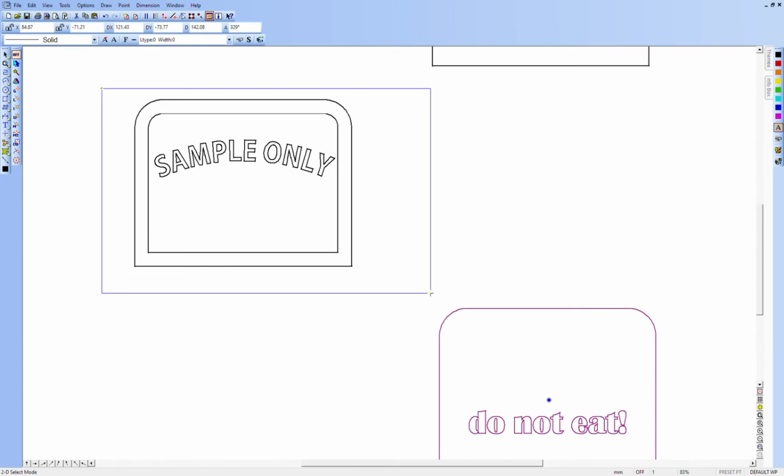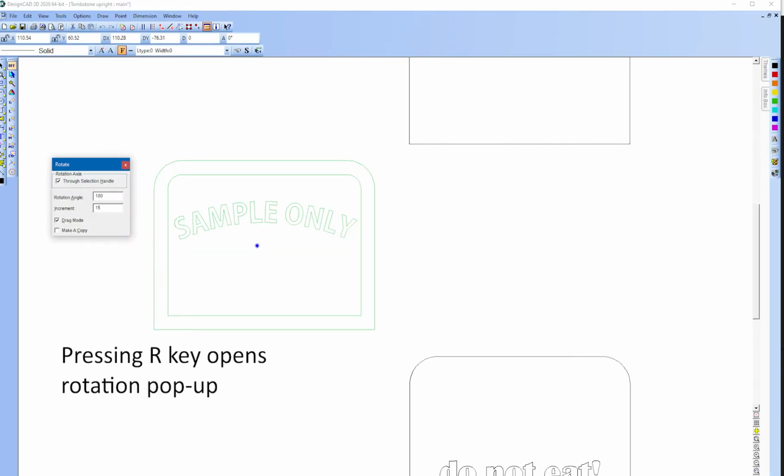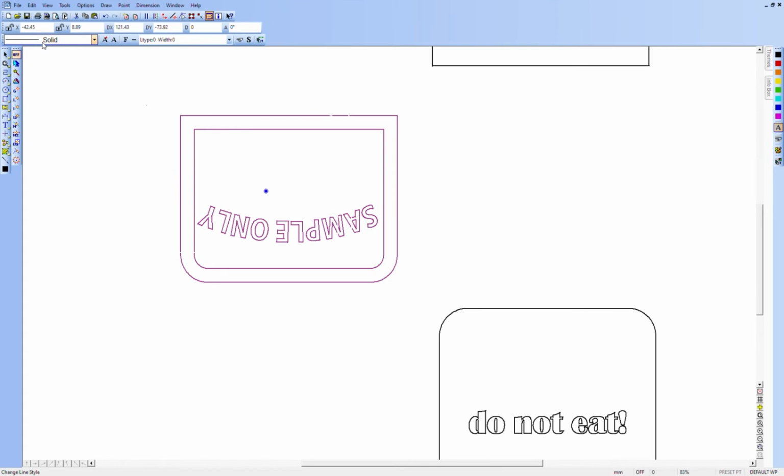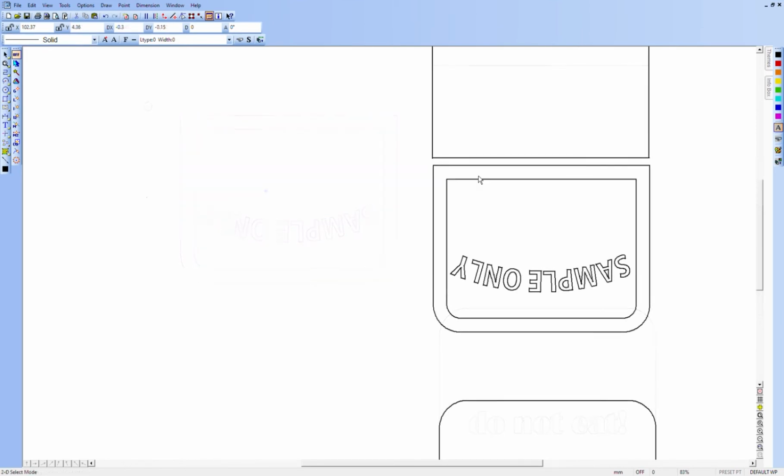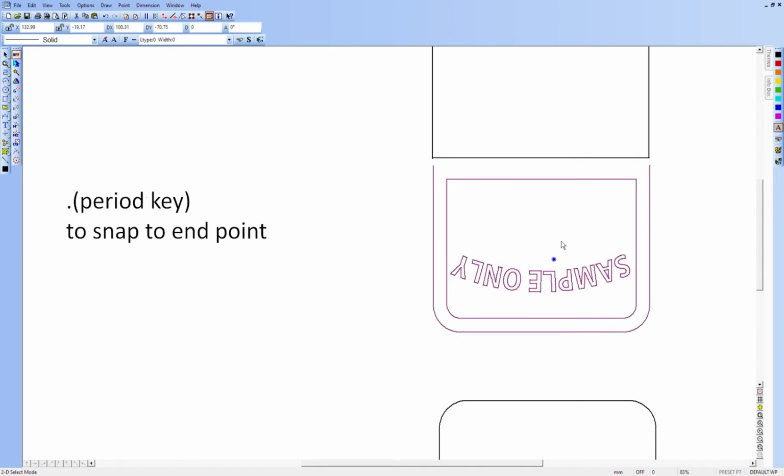But if we select the front piece and rotate it 180 degrees, the mating edges will be exactly the same length. If we just move them together, there will be 2 lines here even though it will only look like one. Instead, we're just going to delete the horizontal at the top of the lower of these 2 pieces. We'll then select the whole front piece by boxing it in. We'll set a handle at the upper right corner of this part.